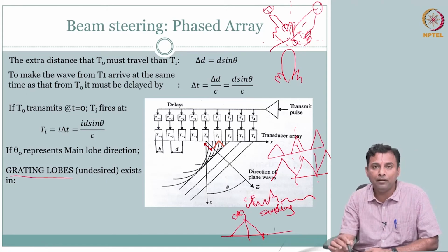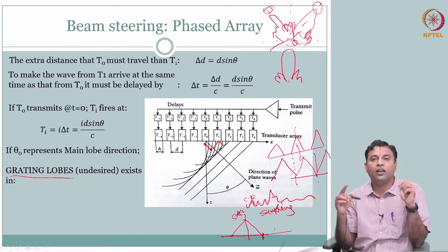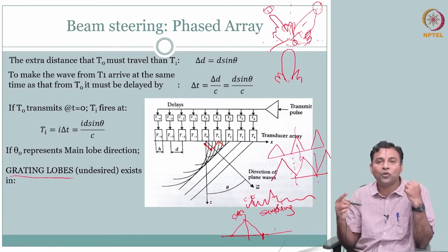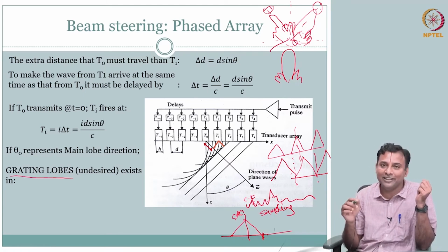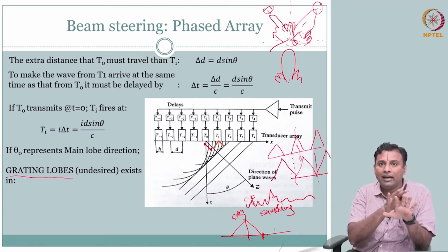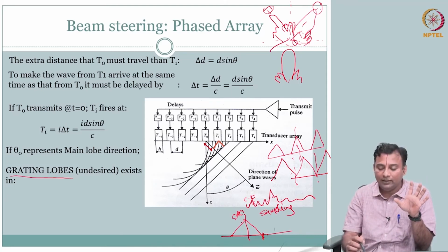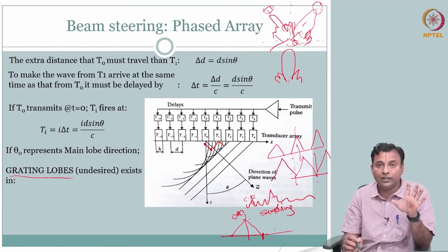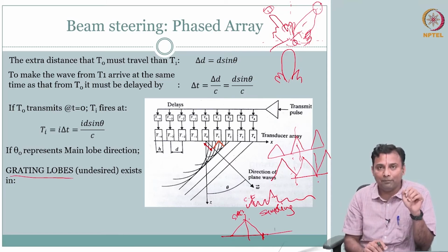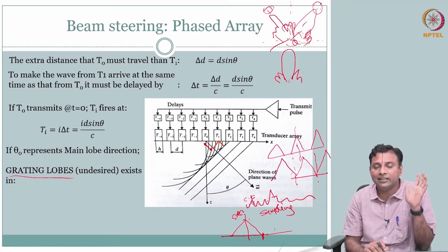So when you undersample, when you go below the Nyquist, you will have overlap, and so we call it high frequency masquerading as low frequency, right? All these textbook definitions. Practically, what is happening? Practically you have replicas of the fundamental spectrum. When you sample, you have to sample such that it is not going to overlap. Okay. So this is what you know from your basic time-based 1D digital signal processing.